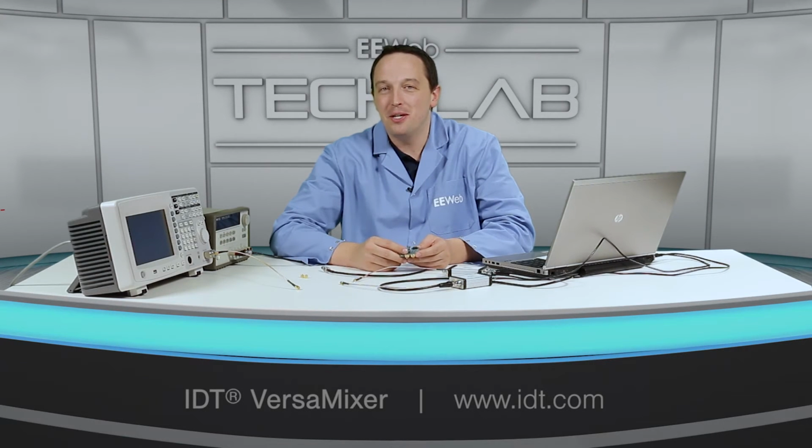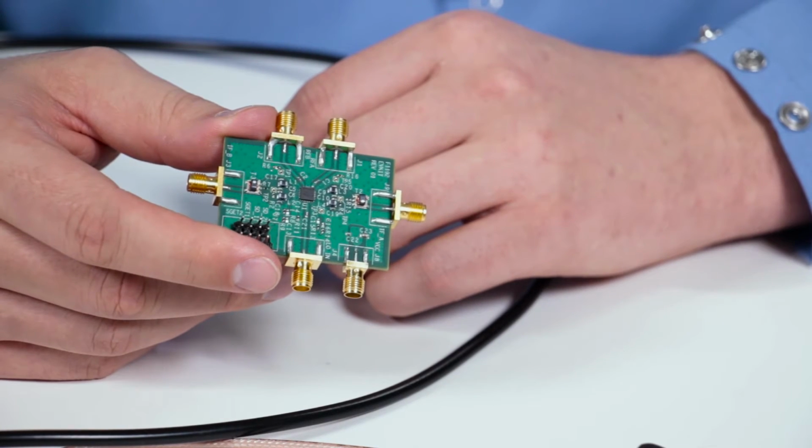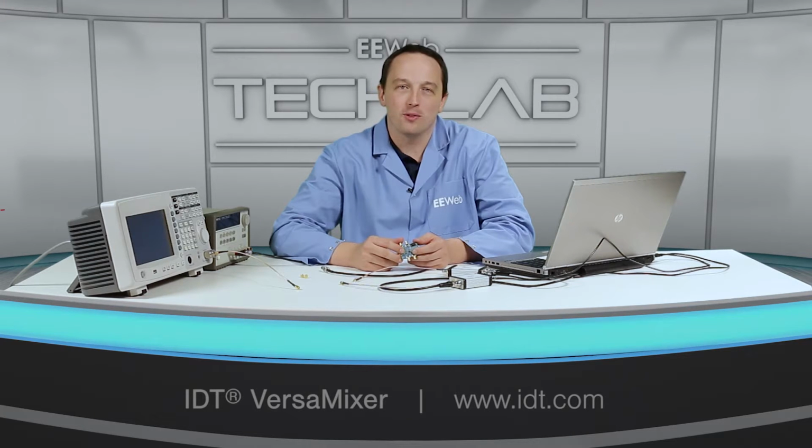I'm Chris Anderson at the EEWeb Tech Lab, where today we'll be looking at the IDT Versa Mixer. Versa Mixer is a wideband, low-power mixer available in single or dual-channel configurations. It can cover RF and IF bandwidths of 400 MHz to 3.8 and 3.6 GHz respectively using a single BOM, letting RF designers deploy the same mixer across a range of technologies.